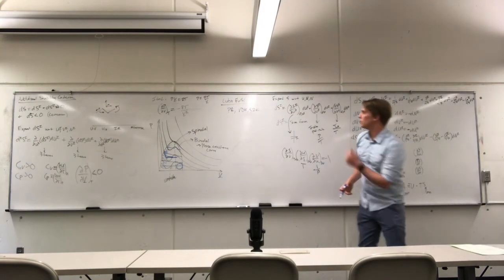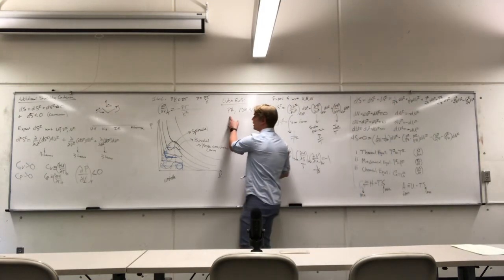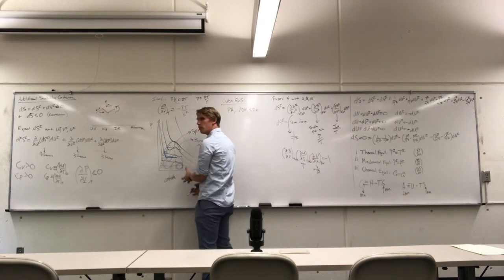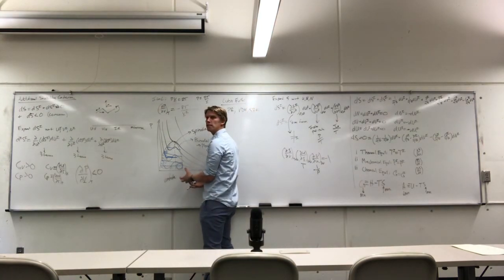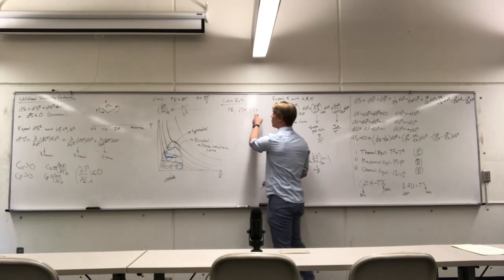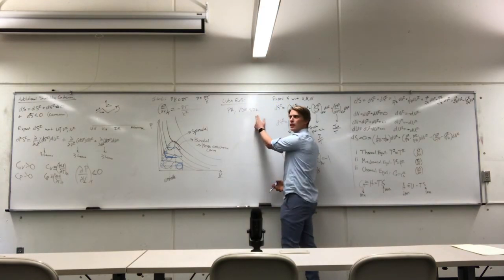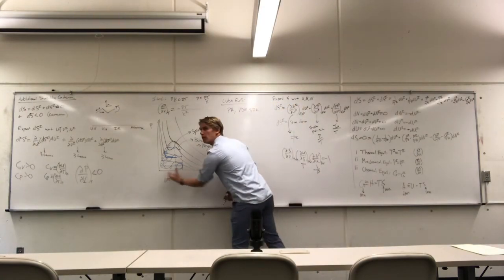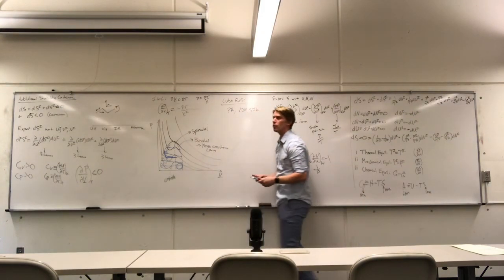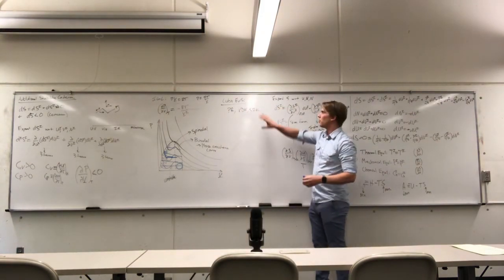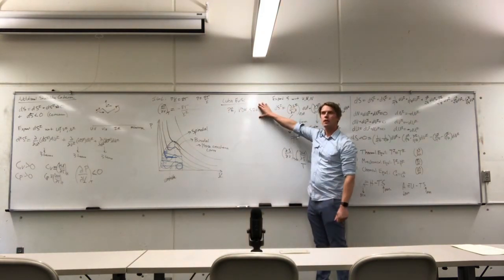And so what we do in these cubic equations of state is we basically take real property data and we fit the coefficients in these equations so that it matches up with the regions that we see in the real fluid properties. Now the basis for these equations has truth in reality, right?